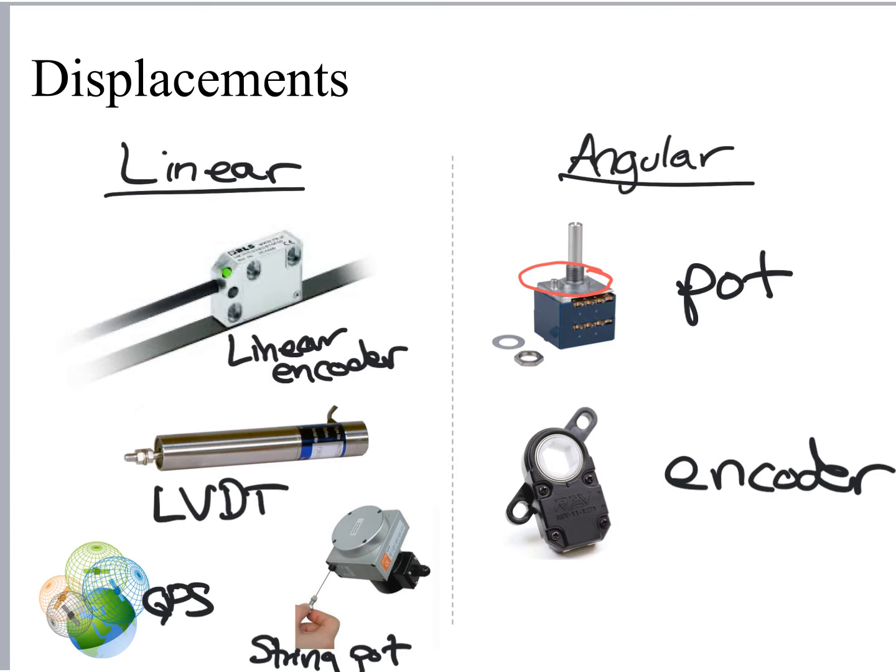If you take 4 of those satellites and you compute the position to each one, and you know the exact position of each of the satellites, then there is only one unique point on the surface of the Earth where you could possibly be, and that's the intersection of the spheres that are the appropriate distance from each satellite. So this is a nice technology, and it allows you to get displacements over an extremely wide range, although your precision is a little bit less tight than it is for some of these other local sensing technologies.